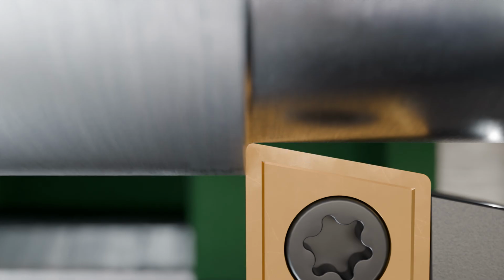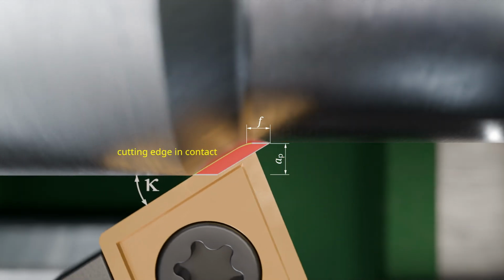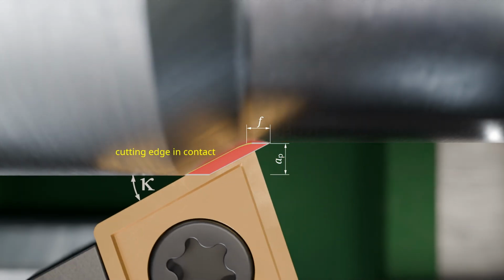The angle formed during turning between the main cutting edge and the workpiece surface to be produced is called the approach angle kappa. The approach angle influences chip breaking, the forces that occur, and consequently the tendency to vibrate. At the same depth of cut, the smaller the approach angle, the longer the cutting edge engaged in the cut and the better the cutting forces are distributed. This reduces the load on the cutting edge and results in thinner chips that break more easily. Additionally, heat dissipation occurs over a longer edge, leading to lower temperatures and reduced wear.